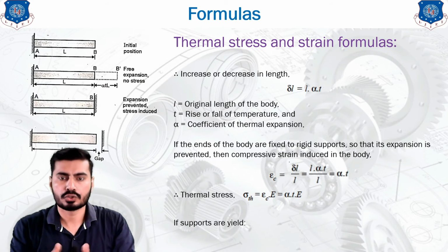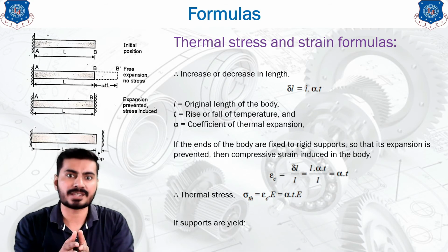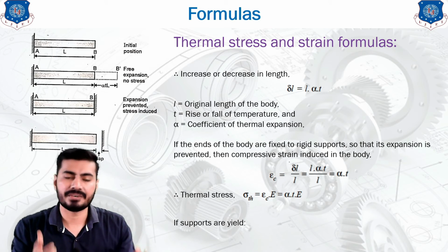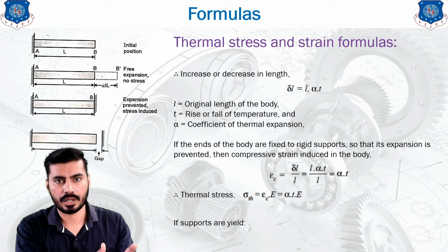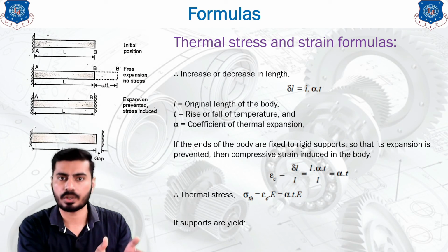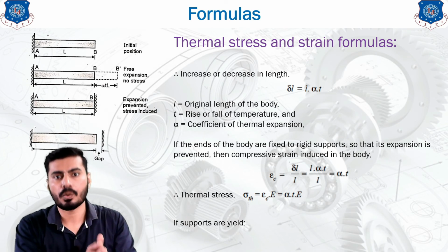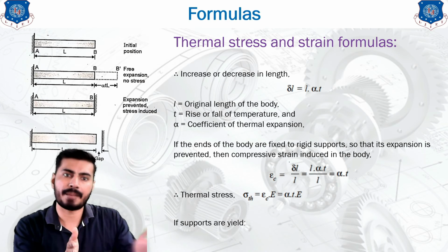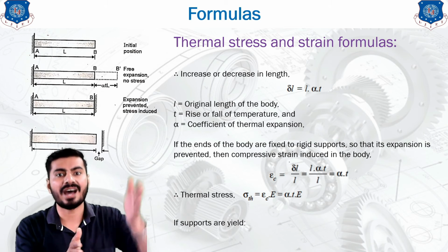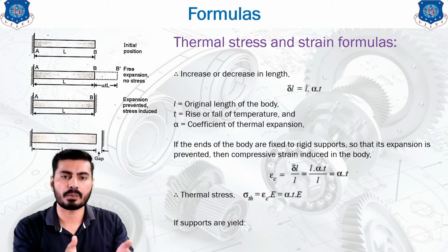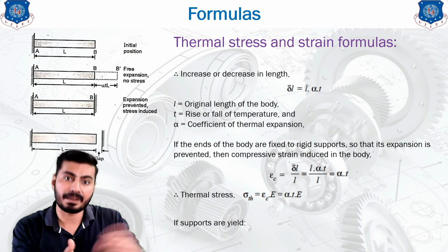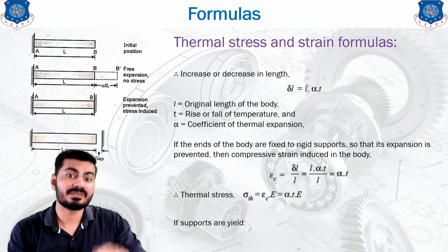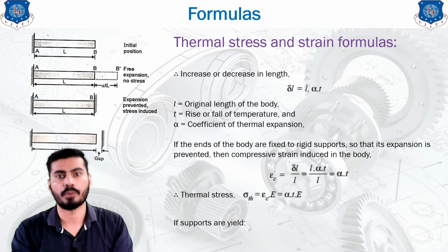itself. Okay, so it will try to expand freely, but what happens, it can undergo the free deformation in the gap. Okay, the gap which is provided between the support and the end of the member. But what happens later on, whenever the gap is filled with the member body, then the supports are fixed, and due to this fixed support, the body cannot expand from that particular extreme limit, and that's why the body will face the resistance from that particular point.